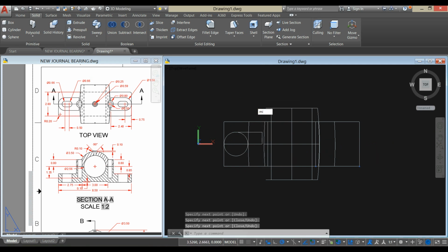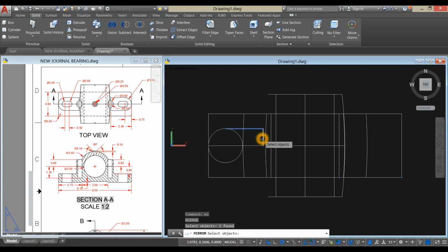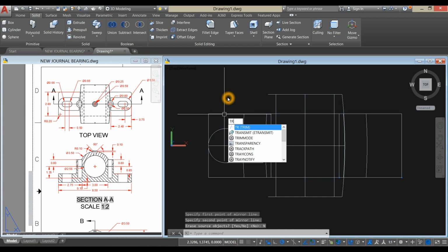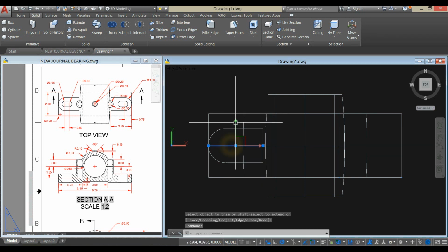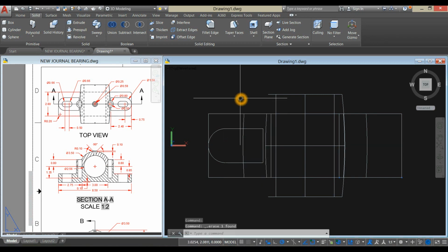I'm just gonna mirror that. Look at mirror line. Type TR for trim command, enter twice. Or just type TR. Select boundaries, right click, and remove that. I'm just gonna delete that. I'm gonna join the segments.